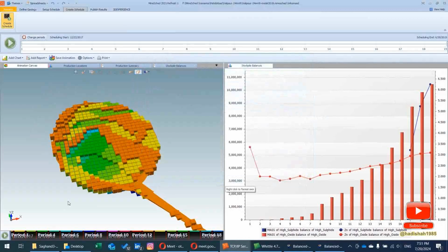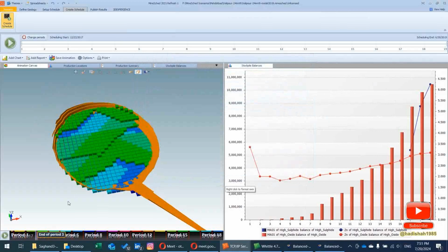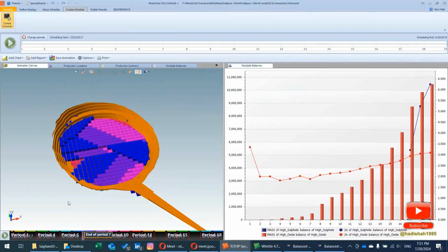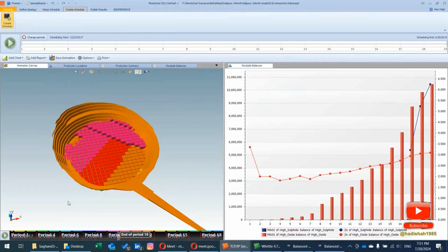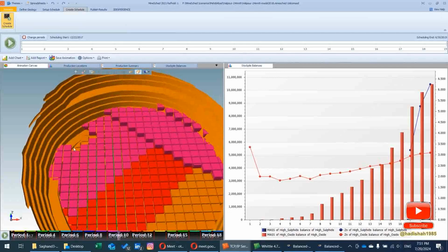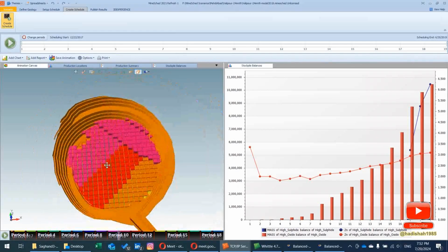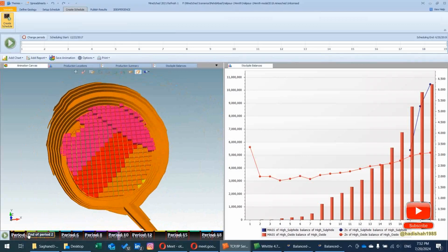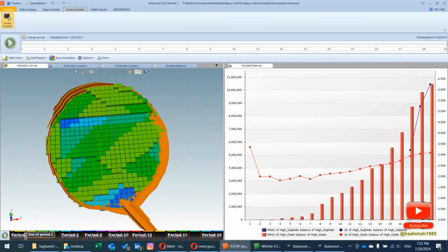When I'm showing the progress of this scenario, you see that the angle of the working phase is changing in direction in azimuth, and the point that each bench is going to be open varies depending on the ramping system.